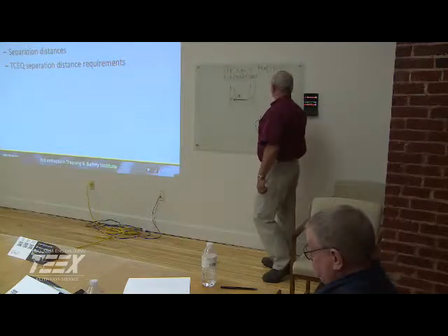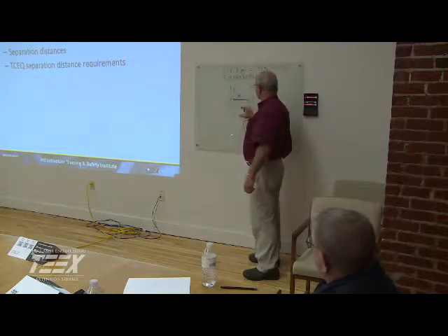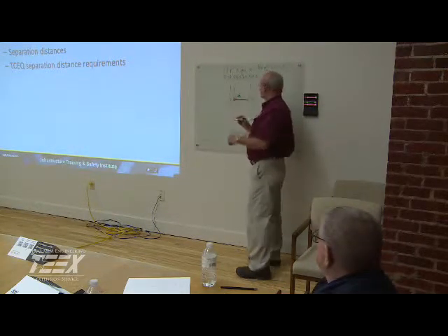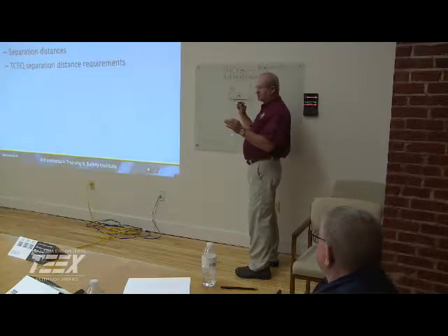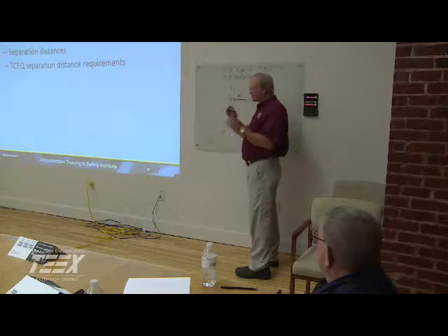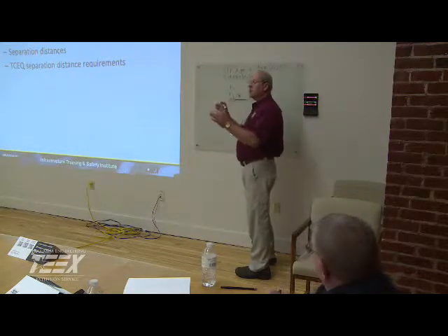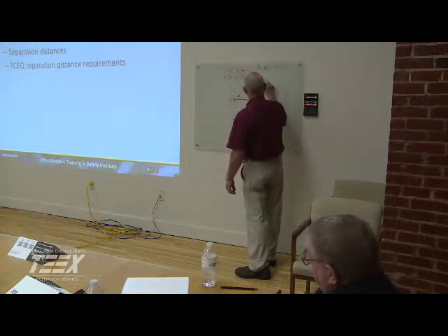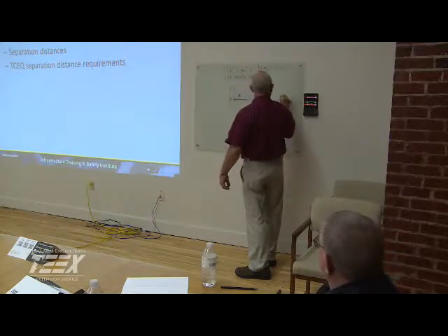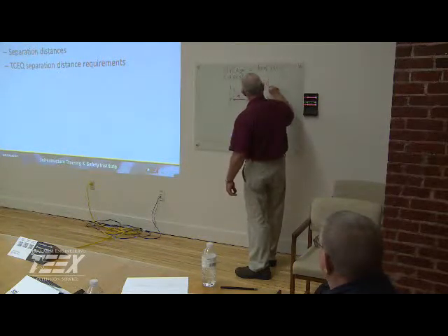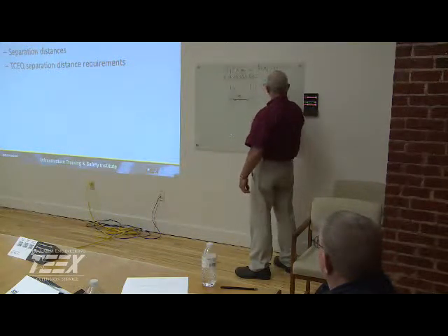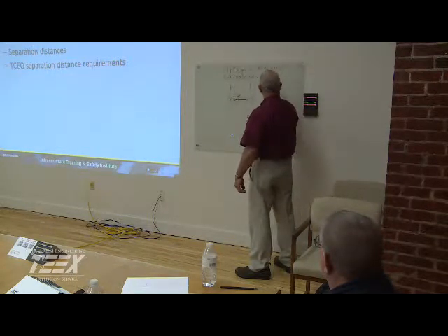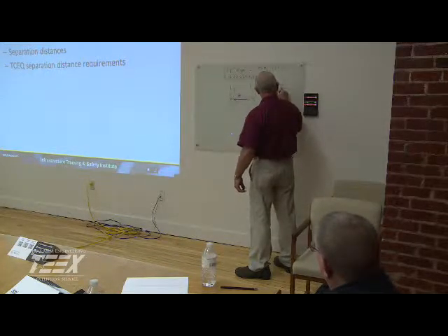Okay? Is that always possible? No. So if I have a water main and a sewer main running parallel, then one of the standards, that's an AWWA standard, but each state might have a different standard. Just to give you an option, there's many options, okay, if this was my water and this was my sewer, then from this wall to this wall is 4 feet, and this way is a minimum of 2 feet.